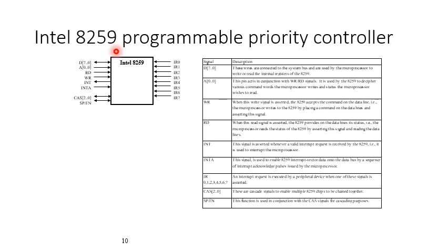Then we have INT, which is asserted whenever there is a valid interrupt request, and INTA is the interrupt acknowledgement. Then CAS 2 to 0 are cascade signals to enable multiple 8259s. If you have another 8259 chip, you can connect it with these pins for cascaded connection.